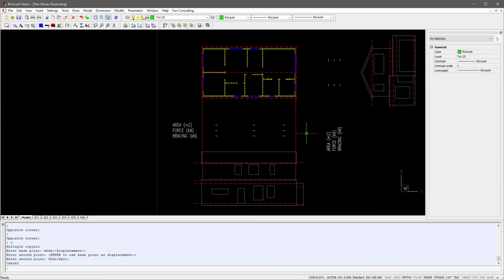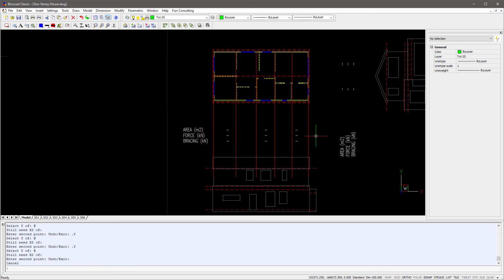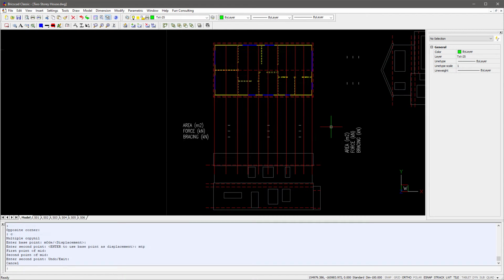The next step is going to be to draw our lines along the walls we can use for bracing. We will begin by drawing along all of them so this part makes the most sense, but as you get a feel for how this works, you'll often be able to skip several parts of this process. The next part is to then draw lines midway between each of these lines which will make up the edges of our area. By doing it this way, we'll get areas that have the brace walls at their centre. Once you've drawn out all the midway lines, you can then delete the internal lines over the walls.